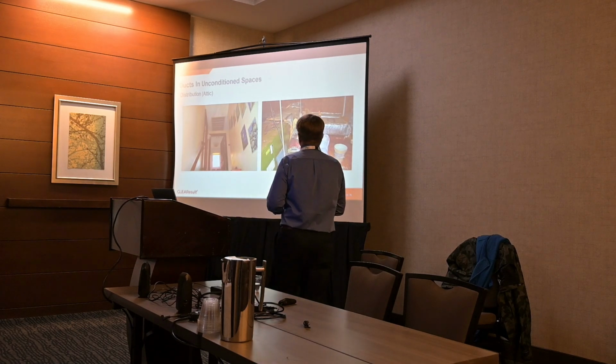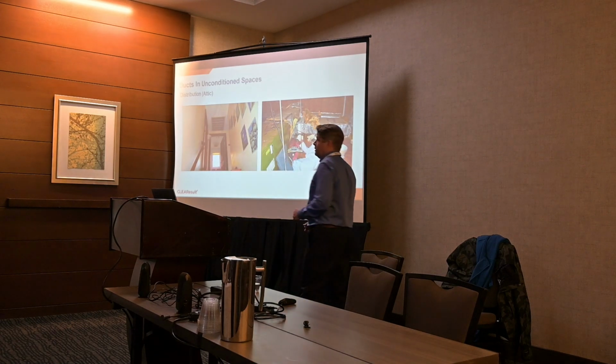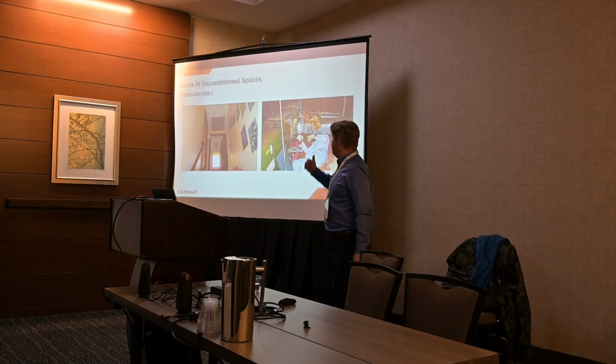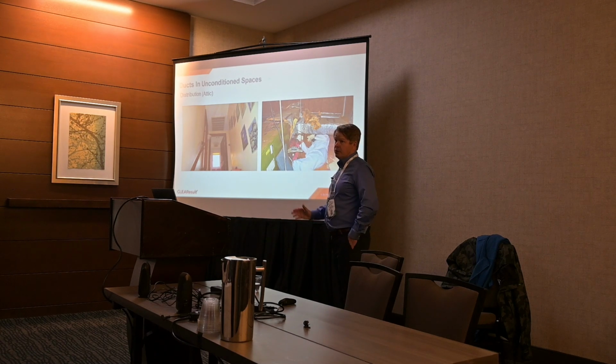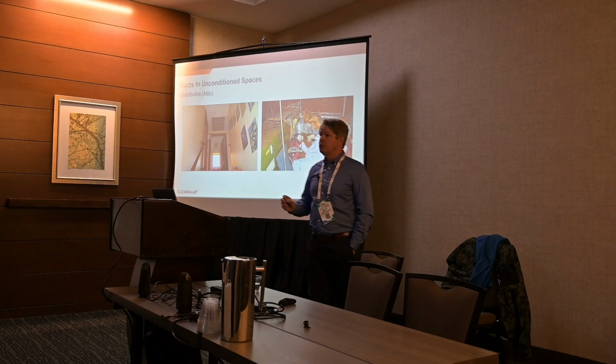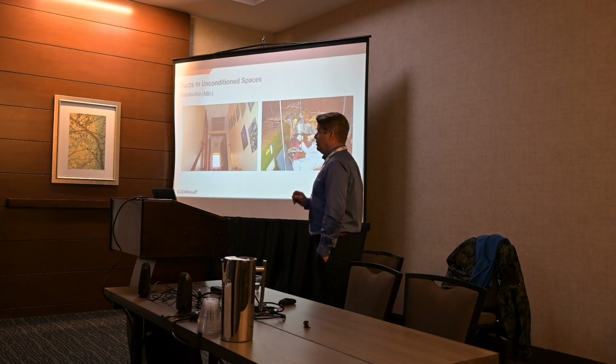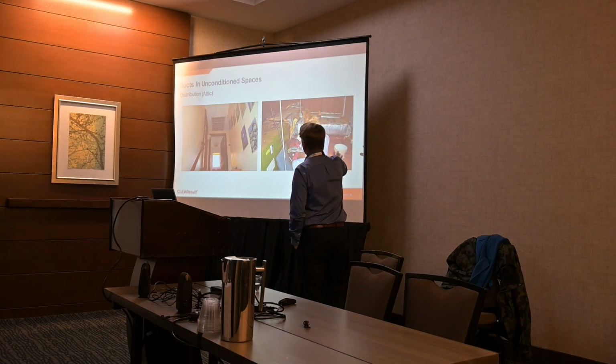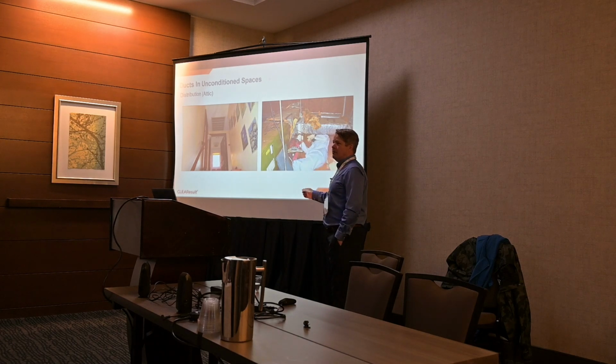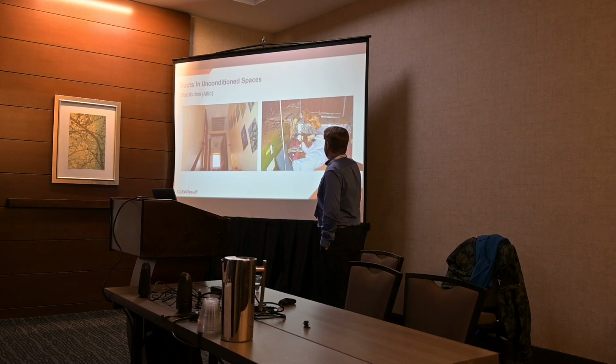Okay, ducts in unconditioned space. There's a lot of different types of unconditioned space, right? There's ventilated attics and garages and ventilated crawl spaces, which is really bad unconditioned space because all the heat that you lose there is actually gone. And then there's basements and unvented crawl spaces and things like that where the duct loss isn't quite as bad.